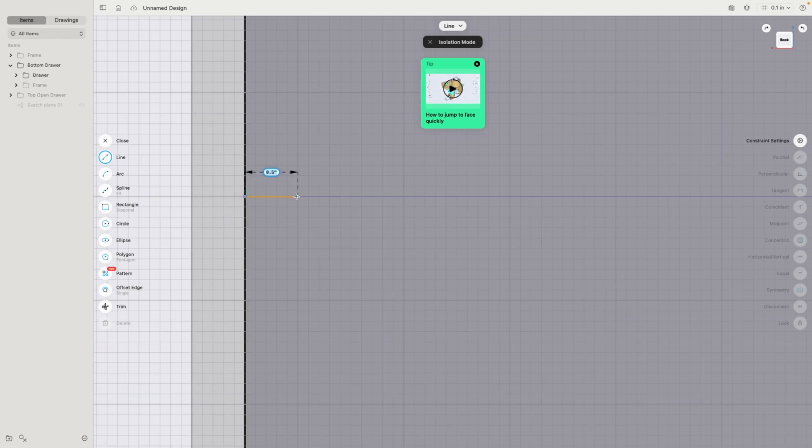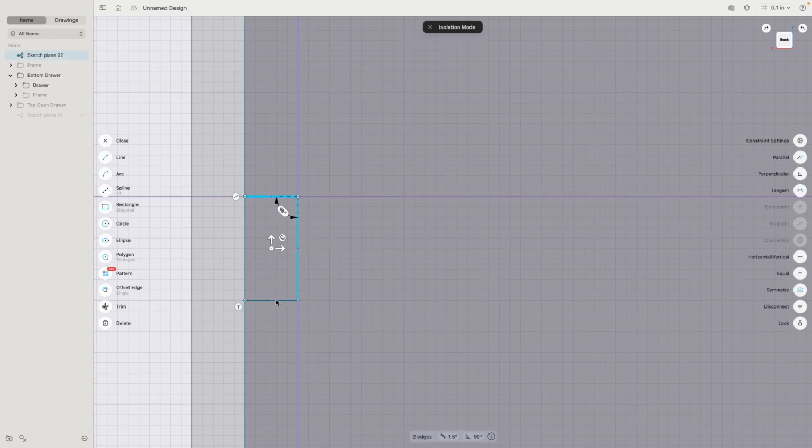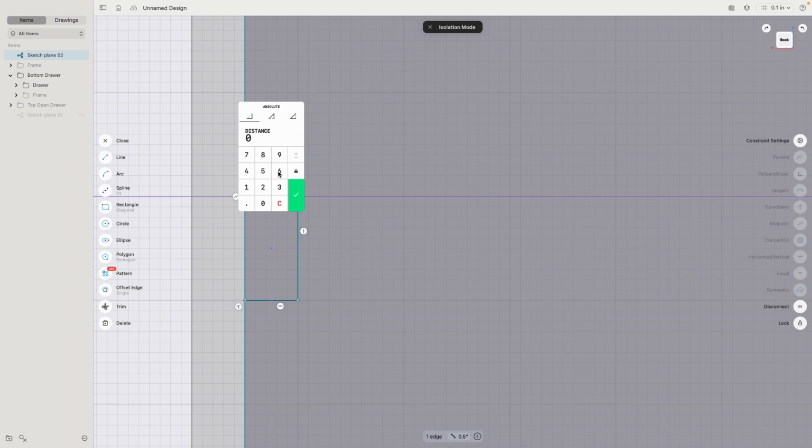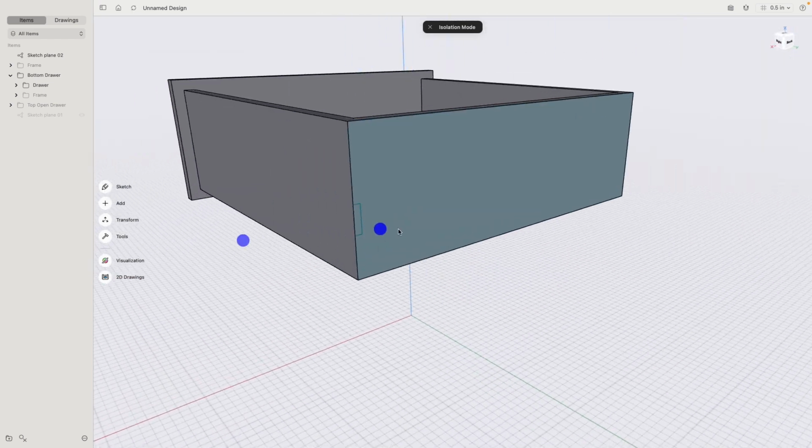So from this midpoint here, I draw a line, 1/2 inch, 1 inch, 1/2 inch, and escape, and escape. These 2, 3 lines I will make vertical, horizontal aligned, and this I will set to 0.25, so 1/2 inch. Very good. Cool, very nice.